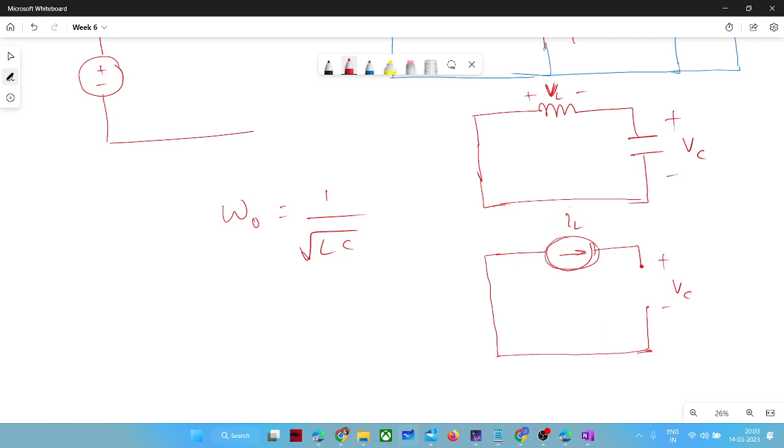So now your inductor has become the current source, but it is seeing an open path. It is not seeing any path to flow, right? So in that case we are exceeding the capacitor limit, right? So in that case the capacitor might get damaged, because your inductor is quite rugged, but the capacitor is what it is.